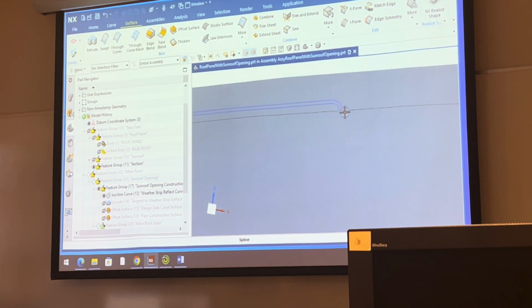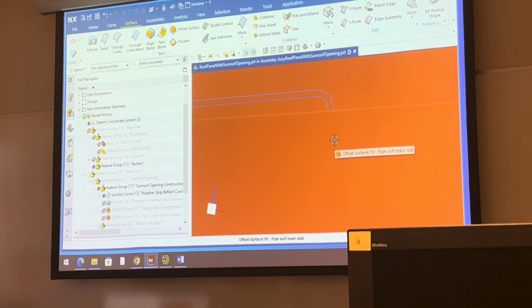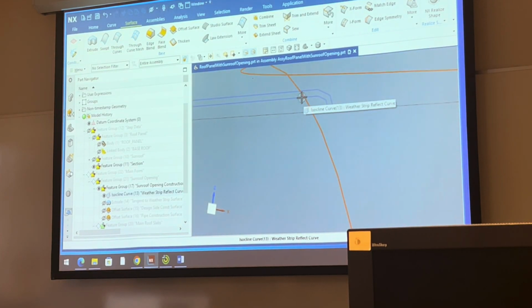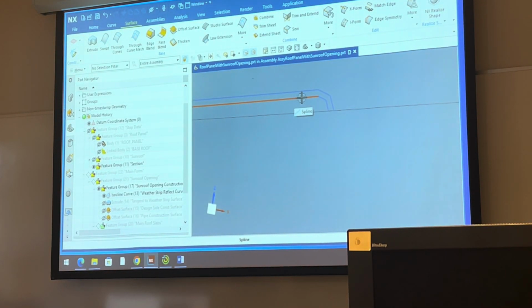Okay. I have a wall that's gonna come up here and then bend across to this one, right? So again, that's our design side right there. And then there's a fillet here, and then there's this wall that we've already made, right? We're gonna use that method that we used before, where we determine where the middle of this fillet is.